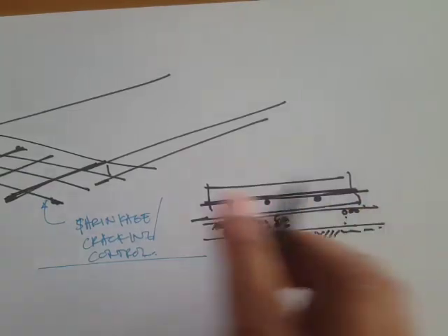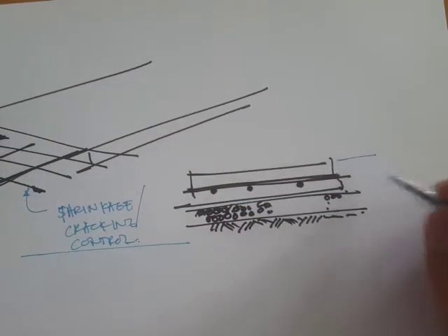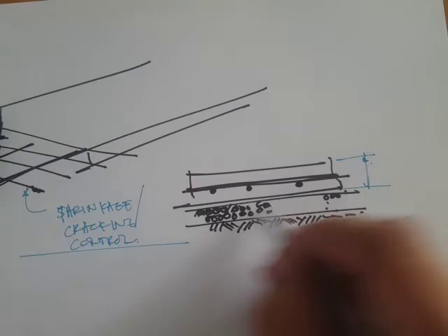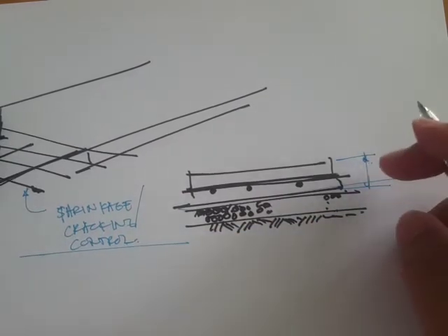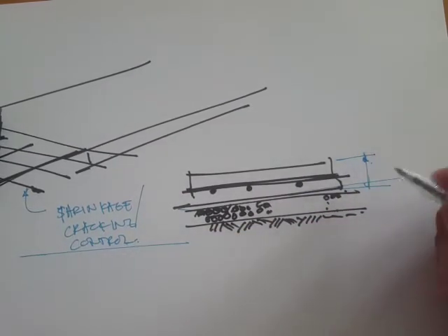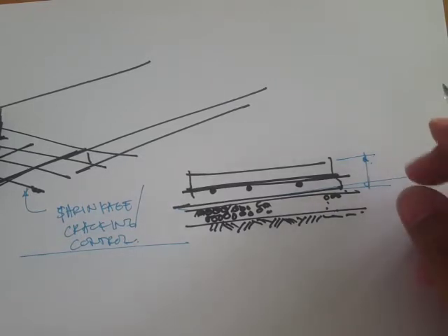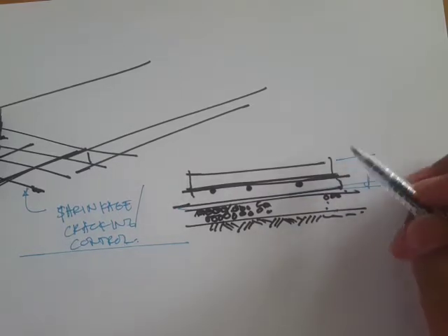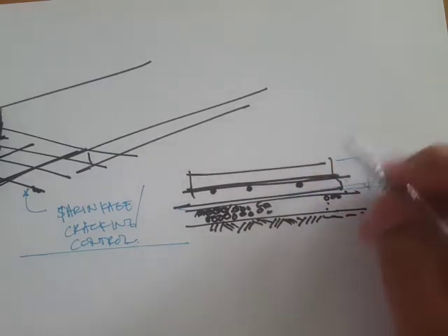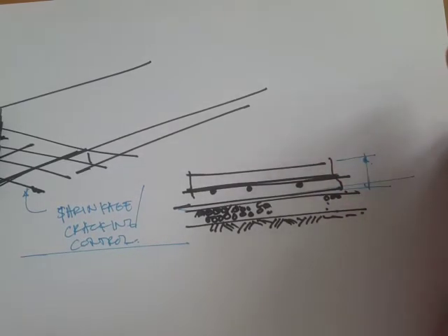Sometimes this is not specified, so that depends. The thickness of the slab refers to this thickness. This is important, and I'd like to emphasize it, because for the thickness of the slab, for example in a bag storage warehouse, if a forklift moves inside the building, the slab has to carry its loading, as well as the stack-up, since the weight of the bags itself is heavy.